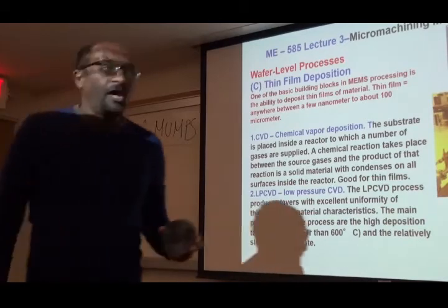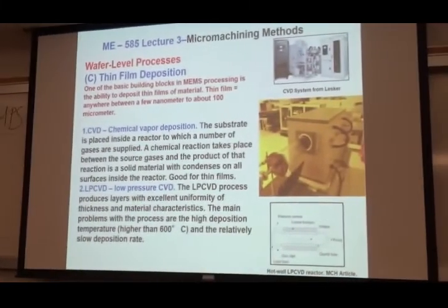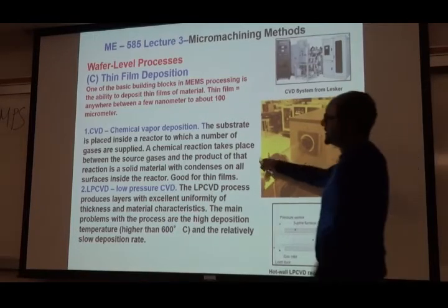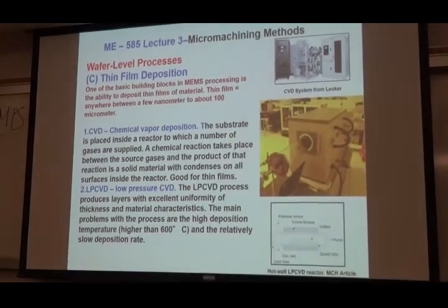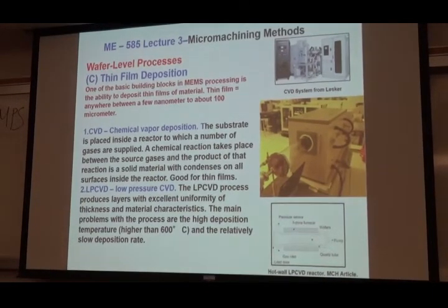Okay? So again, the way that happens, I do another layer of photoresist, and I pattern that and make openings. Wherever I want polysilicon to be deposited, I make openings. And then I put it in that chamber, then polysilicon will nicely deposit on everything. But remember, the photoresist, I can wash it away, right? It's a temporary material, so it gets washed away, but the remaining part is whatever you add. Okay? So that is called CVD. Chemical vapor deposition. It's the most important integral part of any semiconductor process and any MEMS process.